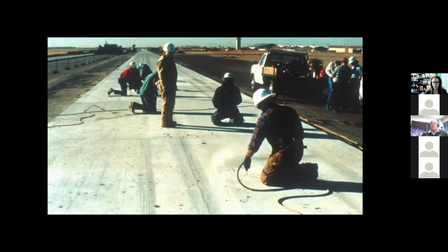What they could have also done, especially in 2020, is they could have ground the surface and then swept the surface and made sure it was clean. And then whether or not they had the right tolerances, if you need to apply an overlay or just a sealer, it depends on where we're at with the surface quality. And actually removing that top layer, you might have sound quality concrete right beneath. It depends on the mixture and why the blisters occurred.